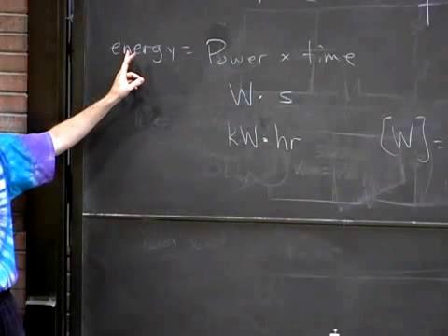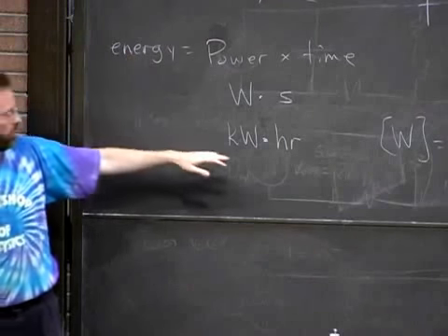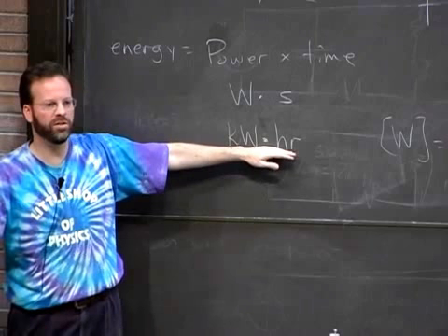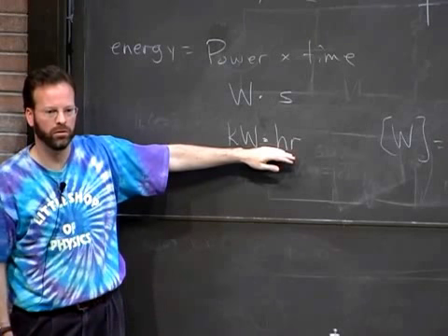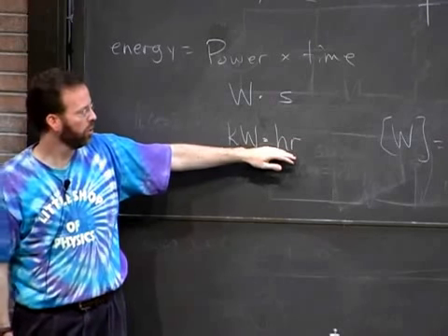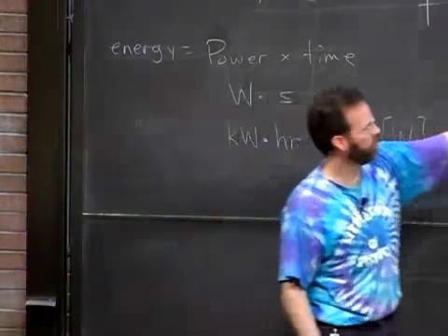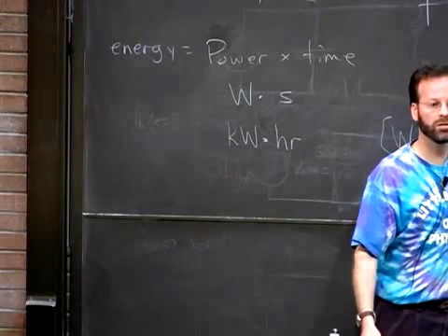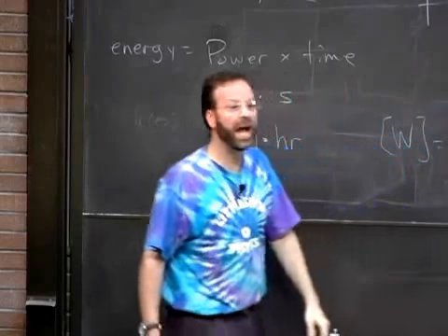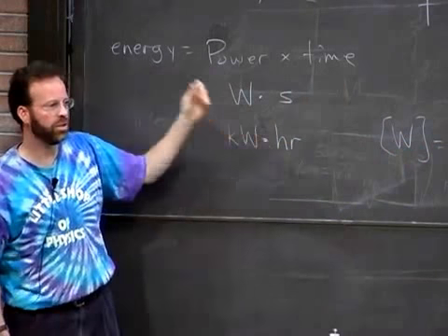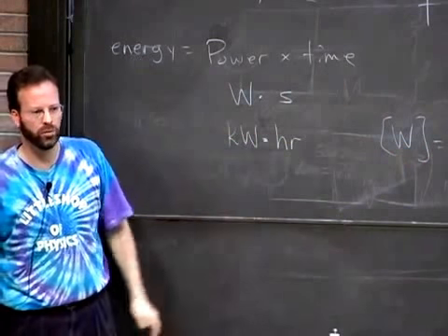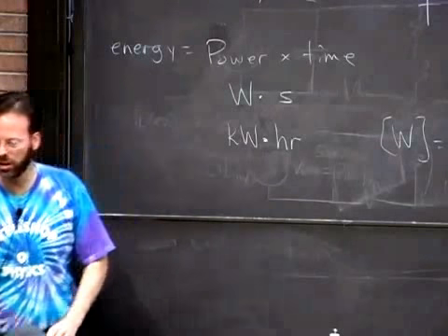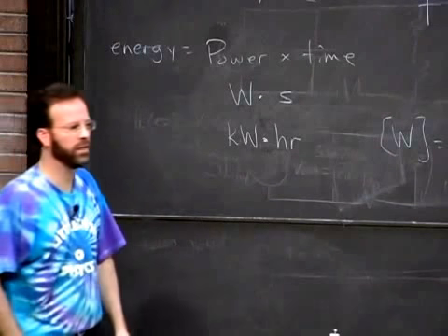That's how much energy is being used. So then that's how they charge you. 15 cents per kilowatt hour. So you can measure your current and your voltage in your circuit, know how much power that appliance uses. And if you run it for an hour, you can figure out how much energy the power company is going to charge you if you want. Or you can buy a kilowatt meter and let it tell you.